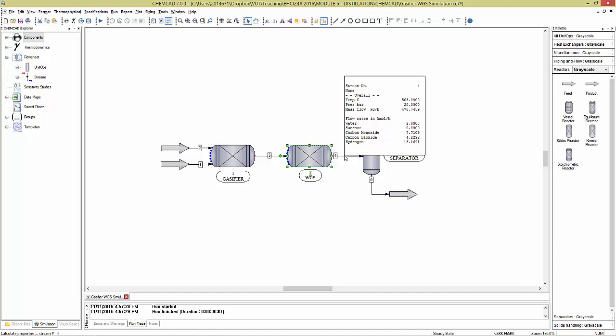So you just have to tune it to be very close to 2. You can always come back to it, because with the recycle coming up, this ratio will keep changing, and then you'll have to come and fine-tune this flow sheet going forward. Please note that the flow sheet as it is, is not representative of what you are going to produce as a flow sheet. We are deciding on the temperature in the reactor here.